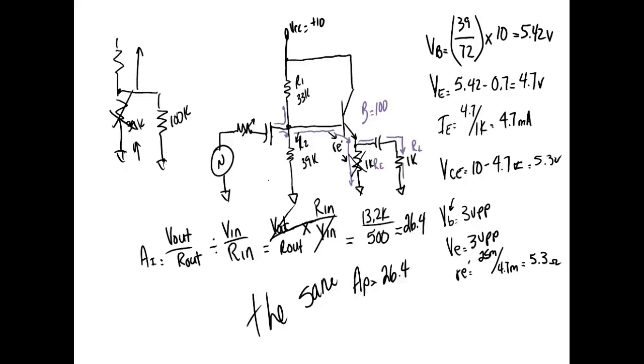What do we anticipate? Is it going to go up or is it going to go down? You're either right or wrong, guys. I mean, it's a 50-50 chance. It's not going to remain the same because there's no current flowing through it anymore. Right? You understand? So that 0.7 of a volt should be non-existent. There's no bias. There's no base current flowing through the emitter. So who says it's going to go up? That's what we're looking at. We're trying to anticipate what's going to happen when